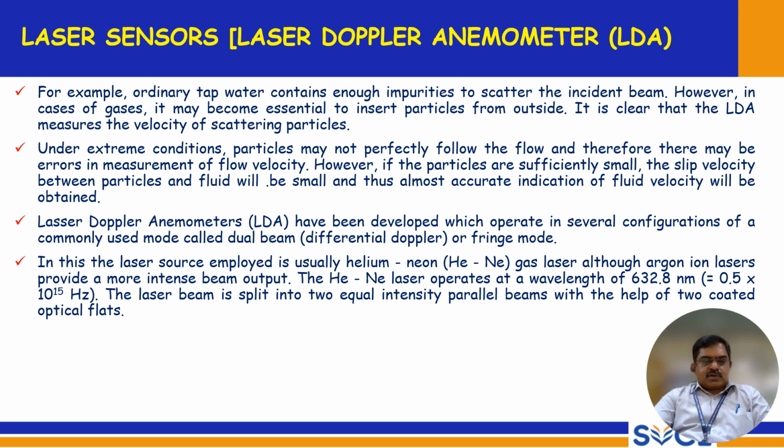So here, as an example, ordinary tap water contains enough impurities to scatter the incident beam. However, in the case of gases, it may become essential to insert particles from outside. It is clear that the LDA measures the velocity of scattering particles.